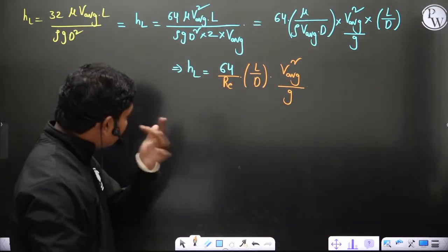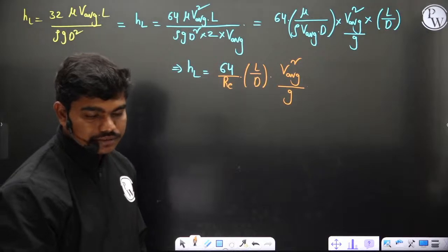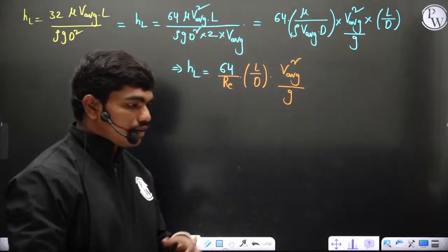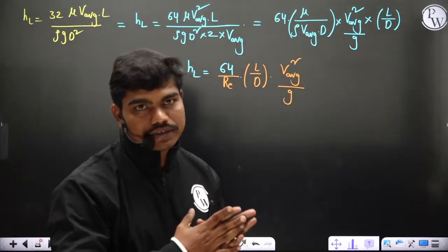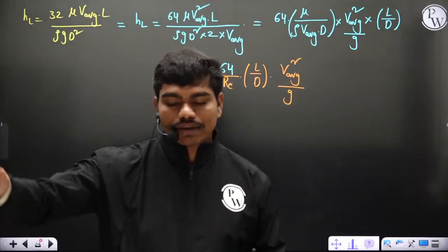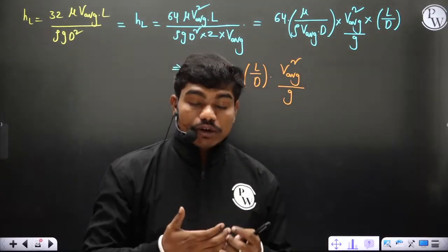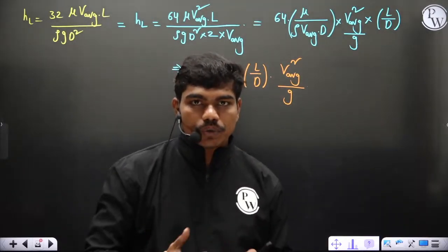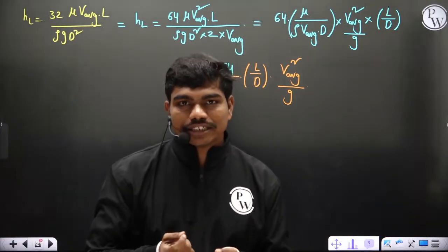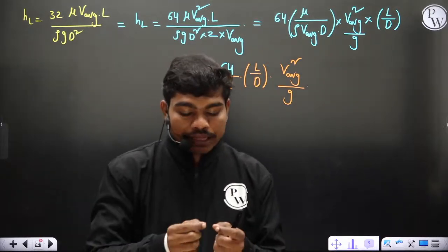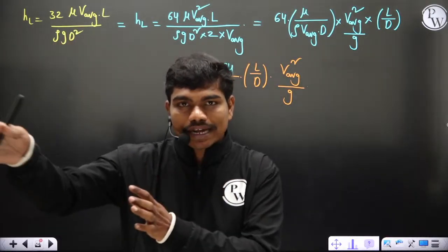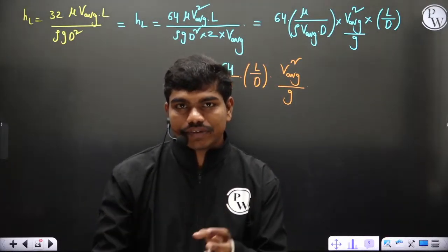See here, why I have done this non-dimensionalization is, once you go to dimensional analysis, you will come to know, if you try to model anything, suppose I want to generate a pipeline for a length of 1000 kilometers. In the lab, before installing the pipeline, you have to do certain testing. It's not possible to generate a pipeline of 1000 kilometers in your lab. So we apply something called dimensional similarity, which we'll see in dimensional analysis. Having certain non-dimensional combinations between the prototype and the model is important. There should be certain similarity between the non-dimensional terms.